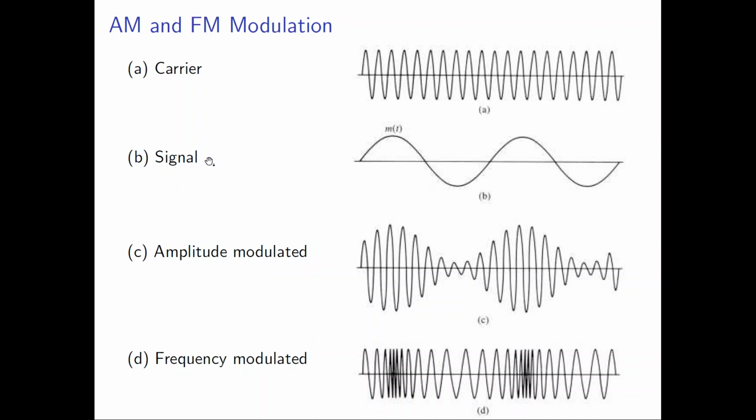So basically, in amplitude modulation, you change the amplitude of the carrier based on the incoming message signal. So the signal you transmit over the air becomes like this, the amplitude modulated one, the third one. You are with me? This is your message, the one you want to transmit. This is what you produce. And this is your carrier.